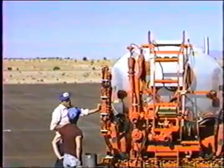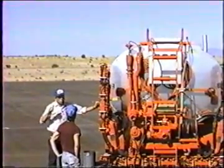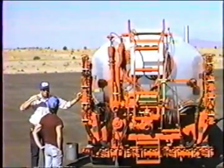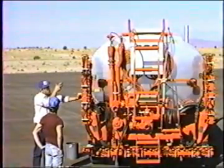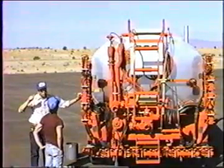That valve is tied directly to the master switch for the spray bar. When we turn the spray bar on, that valve is going to close. Whenever the master switch is turned off, that valve is in the open position. That is, the air is cut to it or relieved from it so that the oil is free to go back into the tank.